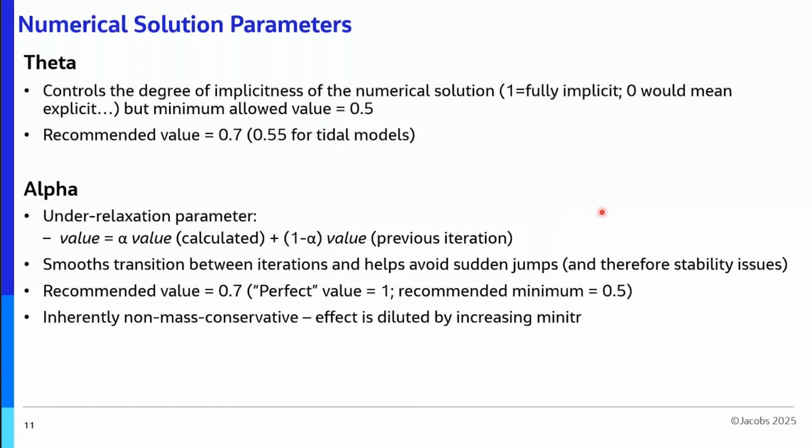Theta is effectively a temporal weighting factor, because you are influencing the current solution, calculated at the given time step, with the solution calculated at the previous time step.